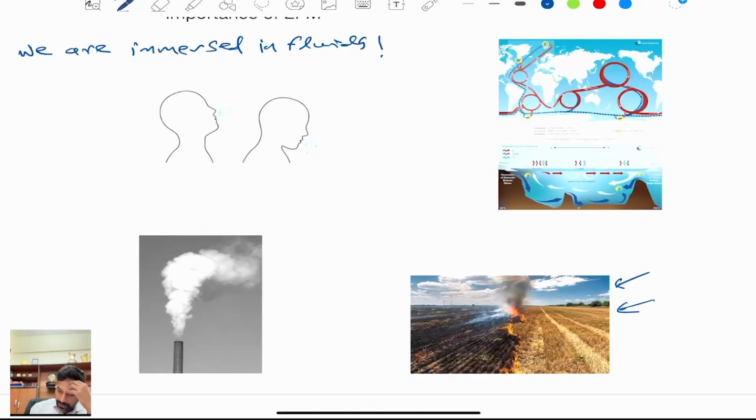Likewise in this case, in example one, where we have this hot gas coming out, it is rising up because of buoyancy, right? And because it's rising up, there is mixing happening from atmospheric air into the hot gas. So because of mixing, now it has to get diluted. So it gets diluted and slowly its concentration decreases, right?